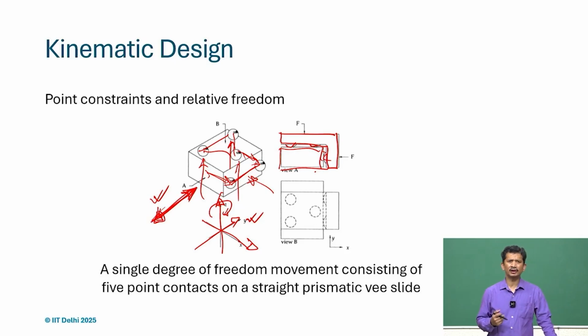One good thing to check is, even if perpendicularity is not maintained, with any tolerances or deviations, it will still work. This works because it is an exactly constrained system, and the same thing will happen in reality, because we can have objects with some deviations, we cannot have exact numbers, but if it is exactly defined, the assembly will not fail.